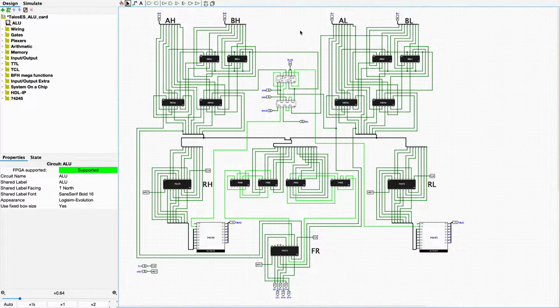So this content will be there, and then during that one cycle the signals will flow through these chips, performing the computations as the signal propagates, and then on the next rising edge of the clock, the output of the ALUs, as well as the output of these logic chips here that compute the flags, those outputs will be latched on the next rising edge of the clock.